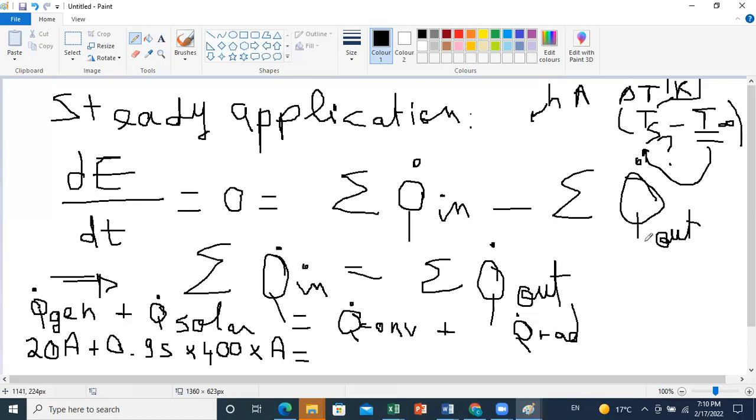I will give you an example. If you have a temperature of 5 degrees and the other 10 degrees, and you want to calculate delta T, you get delta T equal to 5 degrees. Now, if you transform to Kelvin, all you have to do is add 273 to both temperatures. Since you are adding the same amount to both, whenever you do the difference, the 273 will cancel out, and delta T in Kelvin will also be 5 Kelvin. This is why we say that if I know both temperatures, I can use both in Kelvin or both in degrees. This will not affect my result. But because here TS is not known and will be included in other expressions, as in Q radiation, in Kelvin, here also it should be in Kelvin. Okay, so this is why when I do minus T infinity, I should not put minus 25 degrees. I should convert to the Kelvin unit.